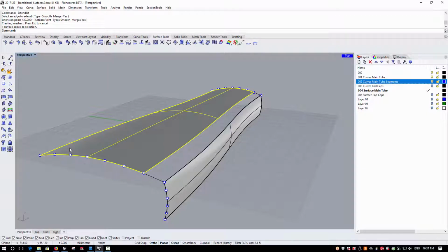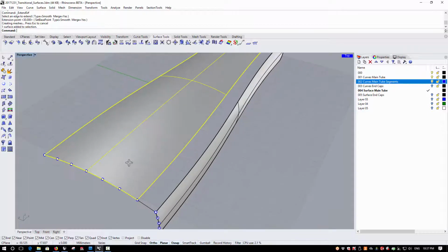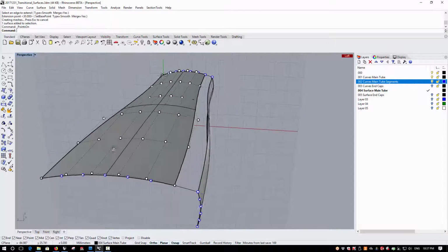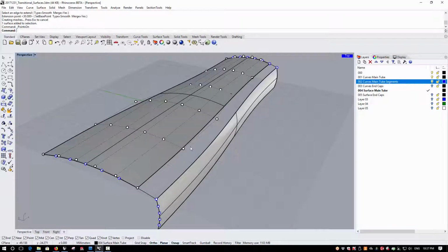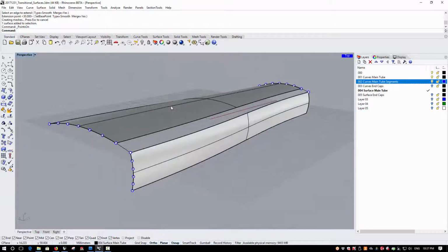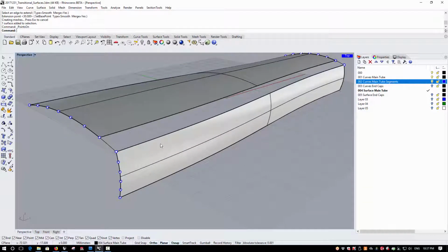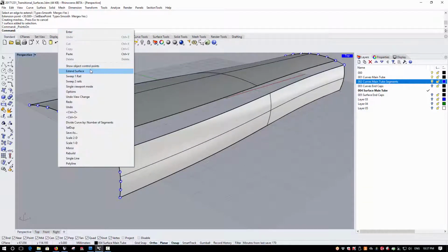Now this does work slightly differently to the result you would have with Move UVN, because it moves all the control points along the surface and keeps all of the control points at equal distances apart, whereas if I actually moved a number of local control points I would maintain the exact control point positions on this side of the surface had I used Move UVN. However, this is a much simpler and straightforward way of quickly pulling back the edge of a surface.